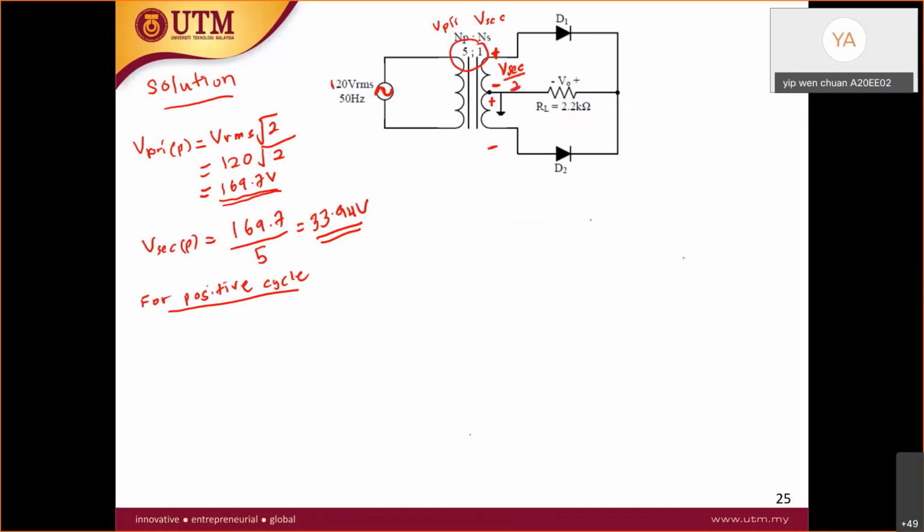For this case, you are already experts. Since the arrow of the diode is the same, which diode is forward biased? Diode 1, D1. Yes, D1 will be forward biased. Like I said, current will go upward from positive and back to negative, then in this direction, plus, minus, to positive V naught and back to the ground. So this is how your loop looks.